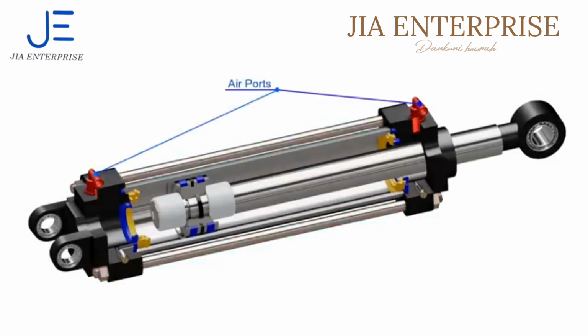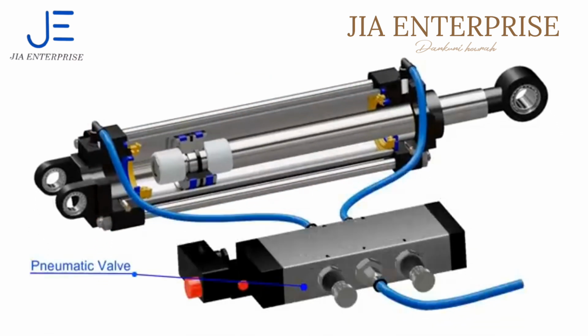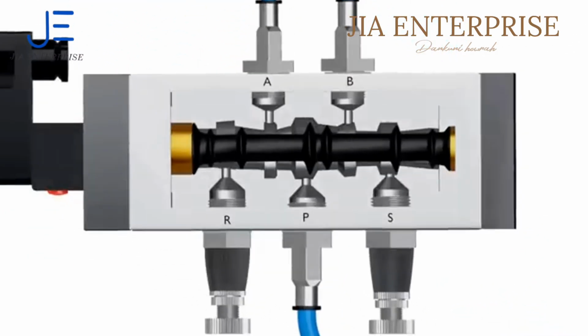Air ports are screwed to the ends, through which compressed gas flows in and out. A pneumatic valve is connected to these air ports using pneumatic hoses. The valve shown here is a 5-port 4-way valve. Ports A and B are connected to the cylinder. Port P is connected to the compressed air supply unit. Ports R and S are exhaust ports to which the pneumatic mufflers are attached.